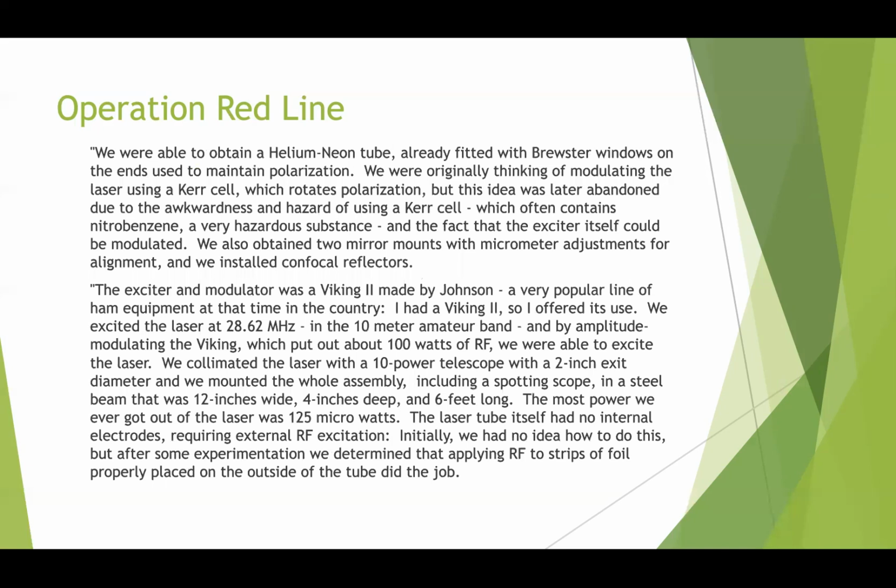So he says, we were able to obtain a helium neon tube already fitted with Brewster windows on the ends used to maintain polarization. We were originally thinking of modulating this laser using a Kerr cell, which rotates polarization. But this idea was later abandoned due to the awkwardness and hazard of using a Kerr cell, which often contains nitrobenzene, a very hazardous substance, and the fact that the exciter itself could be modulated. We also obtained two mirror mounts with micrometer adjustments for alignment, and we installed confocal reflectors.